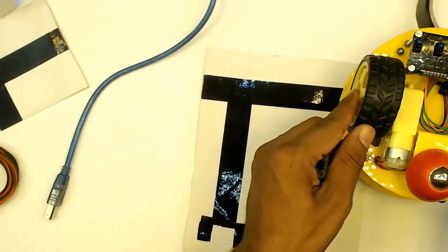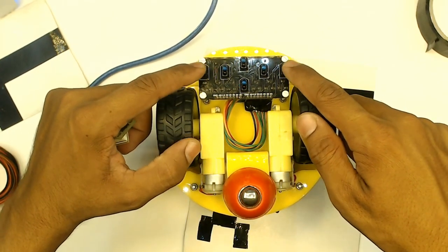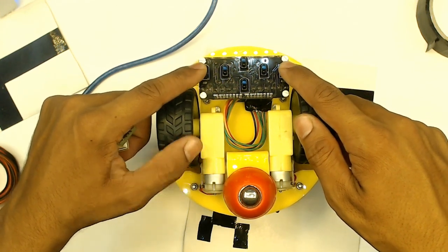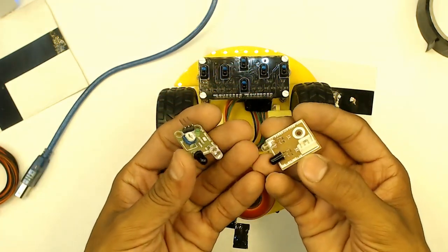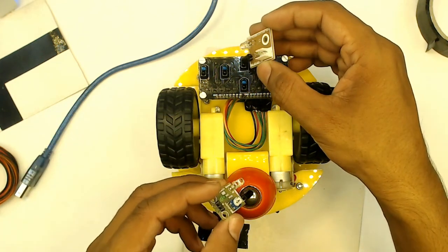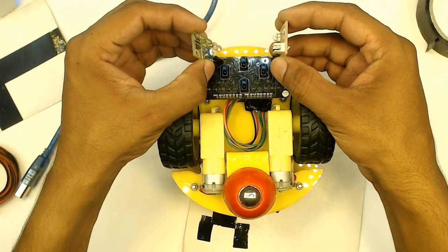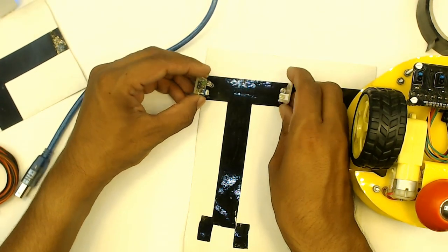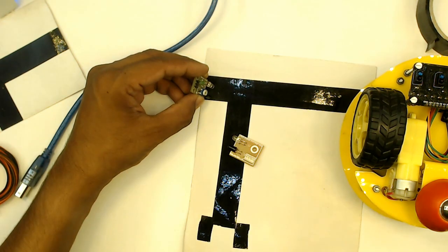Here, sometimes you may find we haven't programmed these last two IR sensors for identification of most of the junctions. If you had a sensor like this in bulk quantity, then you could even place the sensors one on the top side, one on the rear side, and somewhere like this. I would have preferred mounting the sensors like this. I mean, I would have placed them in a T pattern, so that 1, 2, and 3, and the fourth one. This would definitely make things easy.